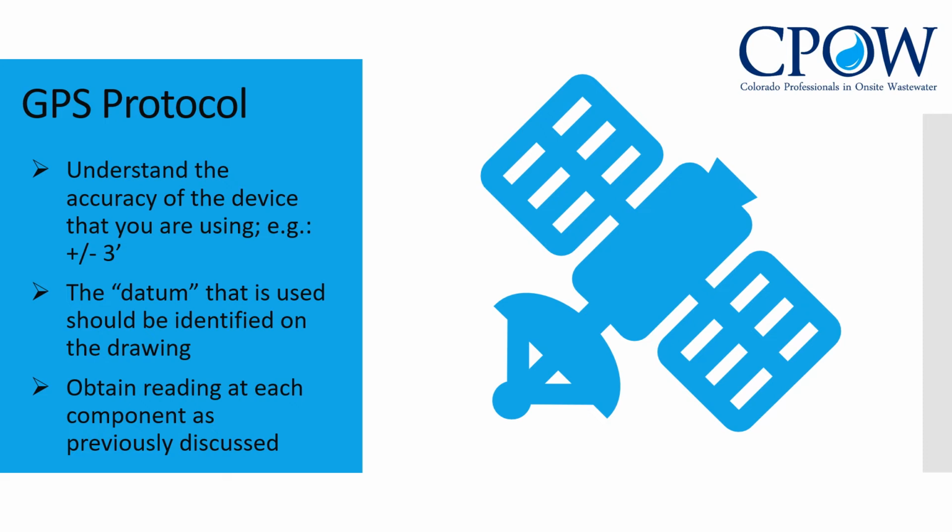GPS can be used to identify component locations. It is important to understand the accuracy of the device that's being used. A typical smartphone is typically accurate to within a 16-foot radius. High-end users boost GPS accuracy with dual frequency receivers and/or augmentation systems that can result in real-time positioning within a few centimeters. If you're trying to locate a septic access lid in the snow, a 16-foot radius is not very helpful. Accuracy can be affected by signal blocking by buildings, bridges, and trees.